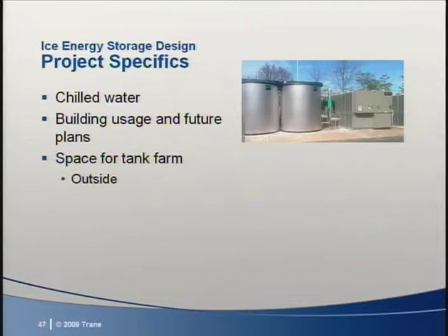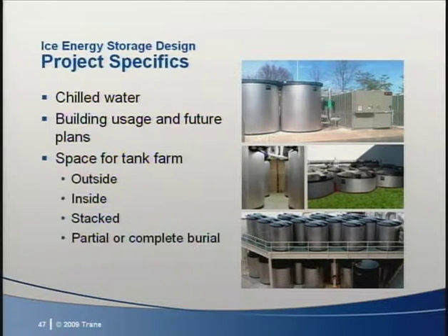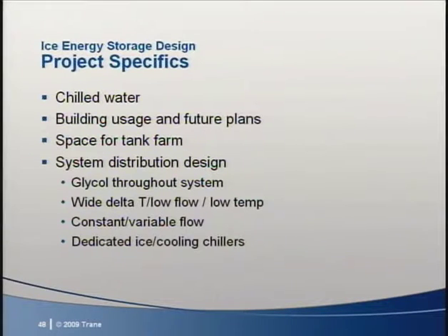One thing that we have seen become a roadblock to adding ice to an HVAC system is tank location. But from what we saw on recent jobs, when the economics work, there's not a better example of where there's a will, there's a way. With a little creativity, it's amazing where ice storage tanks can be located. Susanna will discuss the distribution system considerations a little later. However, one thing to consider for any system with storage is that it's very worthwhile to explore taking advantage of the extended chilled water temperatures that are available and design the system with low supply water temperatures and lower flows.